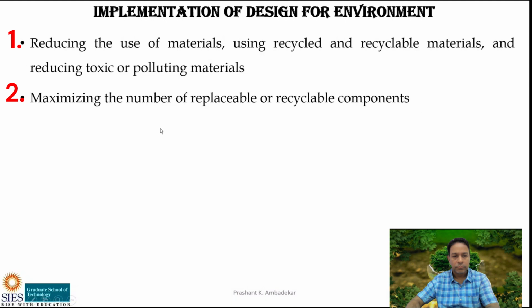So add such components in the product design which are replaceable or recyclable. Now recyclable, you have understood that it should be recycled and then again it can be used. What is replaceable here? Replaceable in the sense, if you are making an assembly of say 50 parts, break that assembly of 50 parts into, I'm just giving a number, 10 sub assemblies. Each assembly is of 5 parts, or break the assembly into 5 parts and each assembly will be of 10 parts. Then, if possible, break those 10 parts also in sub assemblies.